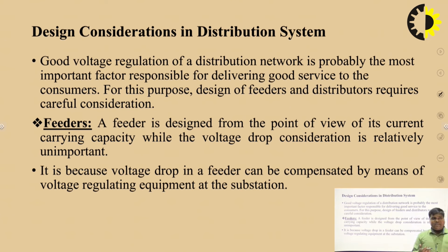Low voltage causes loss of revenue, inefficient lighting, and the possible burning out of motors. High voltage causes lamps to burn out permanently and may cause failure of other appliances as well in the overall system. Hence, a good distribution system should ensure the voltage variation at a consumer's terminals within a suitable range with permissible limits.